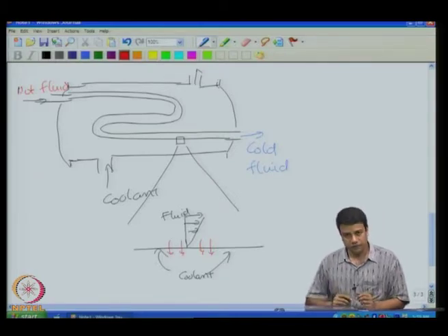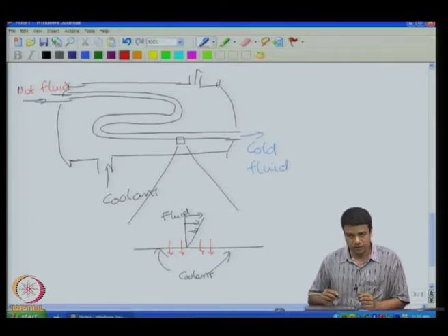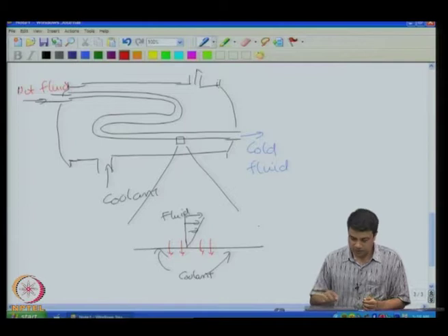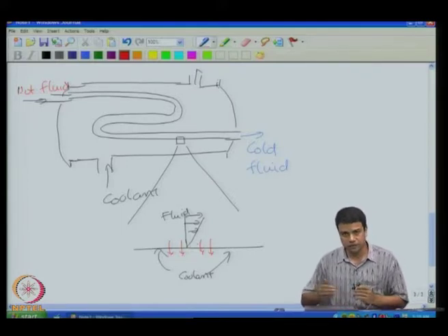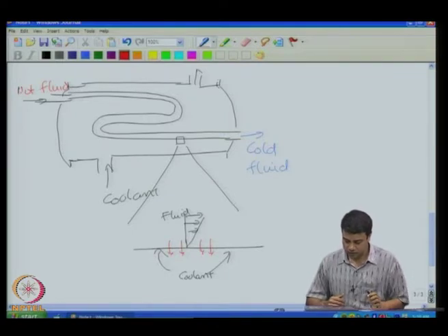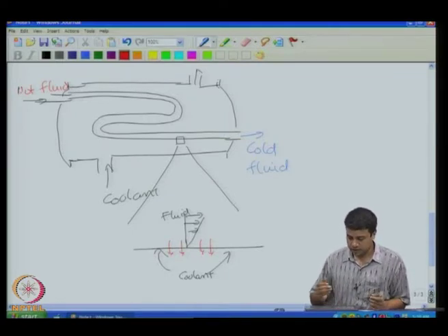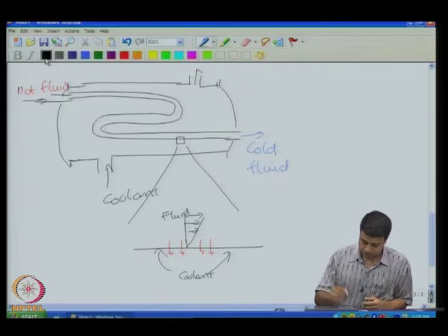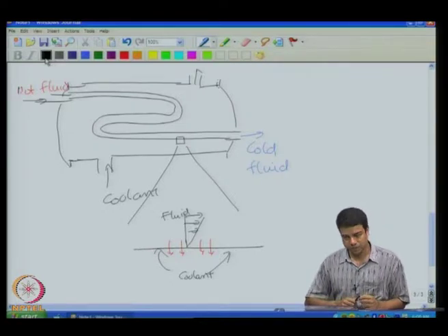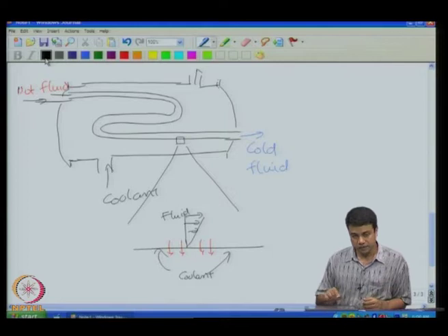So, the transfer of heat will of course depend upon the conditions, the temperature of the fluid inside, the temperature of the fluid outside, as well as the speed with which the fluid is flowing through the tube. So, it is necessary to ensure that you get a sufficient transfer of heat through the interface through the tube, so that the temperature at the outlet is the desired value. And this is a problem of heat transfer through the tube. And actually the conditions are of course changing everywhere along the tube. The temperature is gradually decreasing as you go down the tube. And at each patch of the tube there is some amount of heat transfer that is taking place.